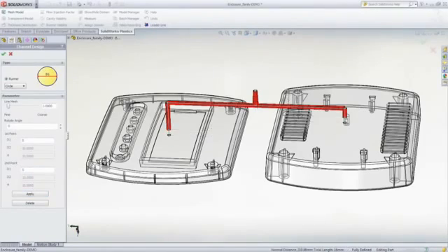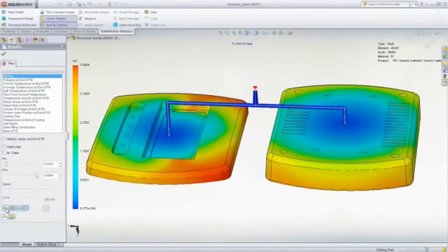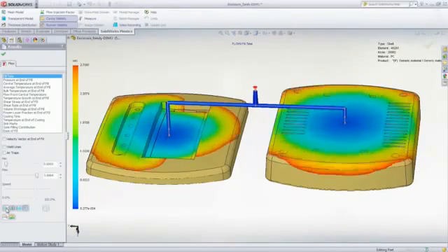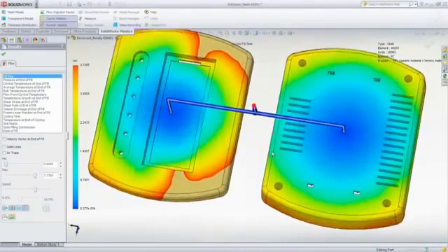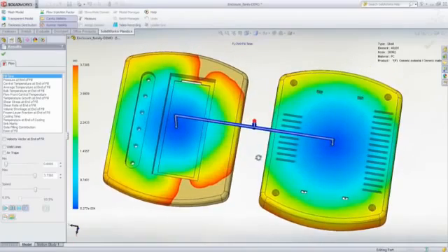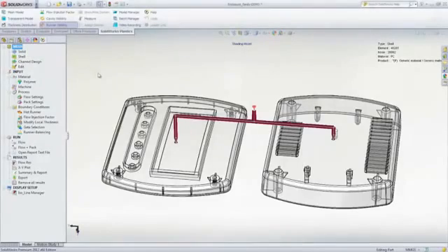However, an additional challenge is introduced because when you mold two or more parts of differing geometry in the same mold, your goal is to get all the mold cavities to fill at the same time. And this can be virtually impossible to achieve without the use of SolidWorks plastic simulation. The good news is that you can perform a runner balancing analysis in SolidWorks Plastics.